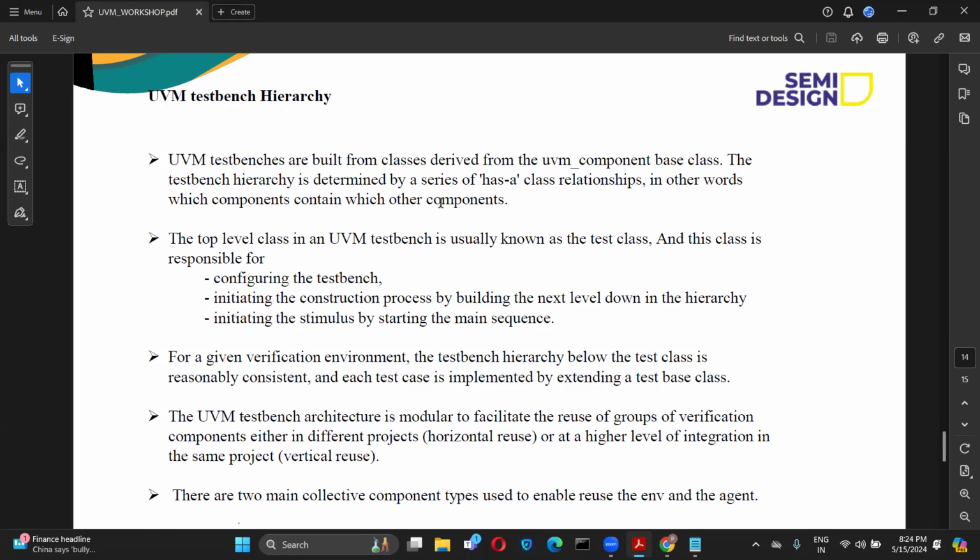Okay. If you see the architecture, you will get an idea of what is connected from where to where. But for now, we will create instances of the driver, monitor, and every class, and we will make the port connections there. All the driver, monitor, and monitor to coverage port connections. Then we will run the test cases there.